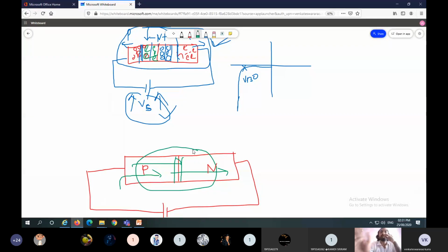So if we decrease charge density, which means if we decrease the doping level, we can achieve only one state. It means the device can block high voltage, but it does not allow high current. It satisfies only one requirement. It does not satisfy the other requirement. The other requirement is that we need to allow high current. To allow high current, we need to increase the doping level.